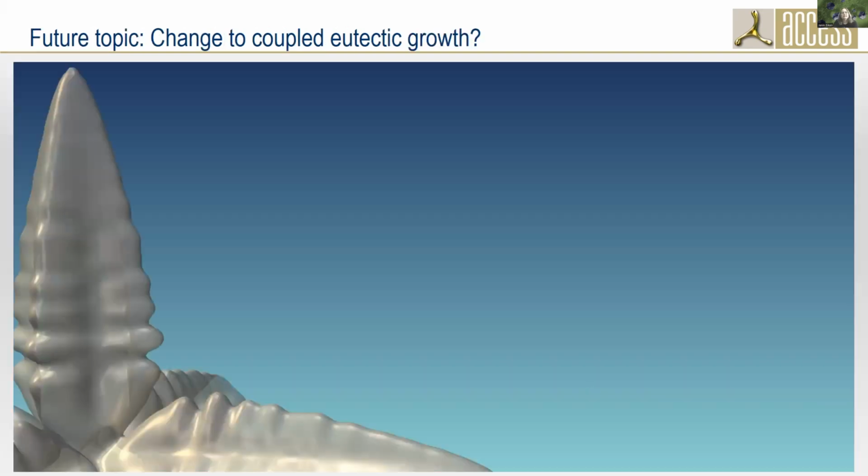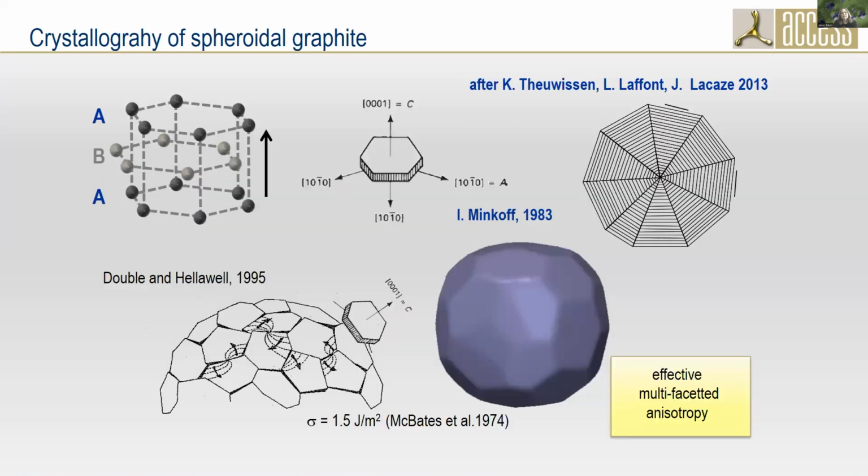Okay. Now, I still want to show you this. When I plot this, it is not the interfacial energy, this is just a Wulff plot. So this is the morphology it would have if it were in equilibrium, but of course it's not in equilibrium during growth, and so during growth it may look very different and may have very different growth forms.